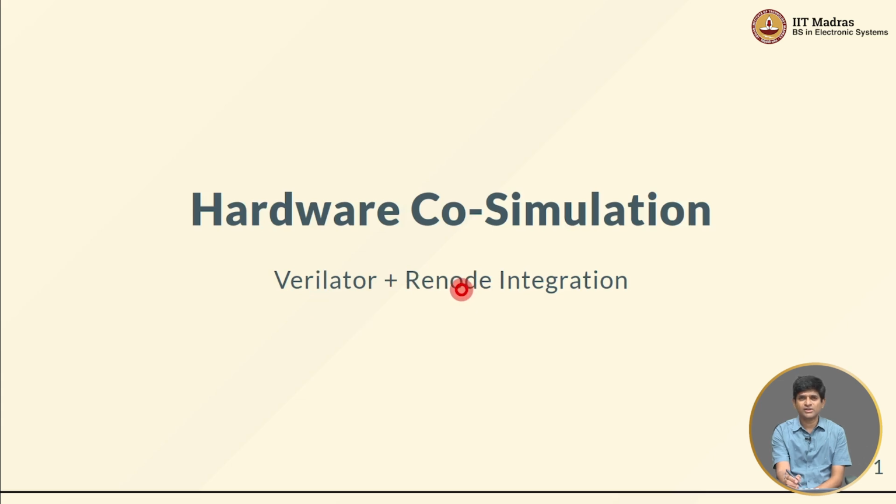This is not exactly the same as what's called a hardware-in-the-loop simulation. It's a co-simulation because what we are doing over here is we have a simulation of the hardware and the system that is sort of emulating the processor on which the software is getting emulated, and we are sort of integrating the two together. So once again, there is this confusion regarding the term, should it be simulation, emulation, co-simulation, what are all these things?